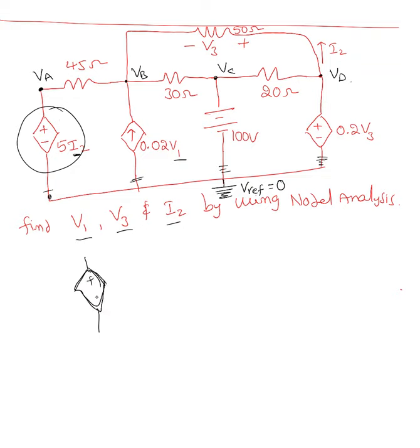If you have plus and minus, that indicates that that's a voltage source. And if you have multiplication I, so this voltage source depends upon the current, so it's a current dependent voltage source. If you have something like this here, that is a voltage source, but it is depending upon the voltage. That's a voltage dependent voltage source. Okay, so here I can tell, VA minus 0 equal to 5I2. I don't need to apply KCL. VA, I can clearly see VA equal to 5I2.